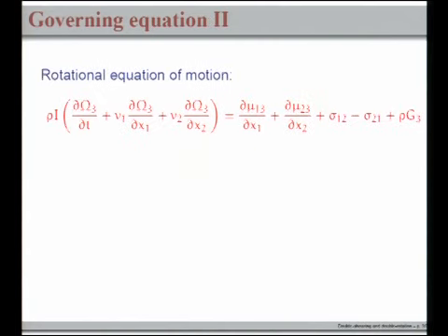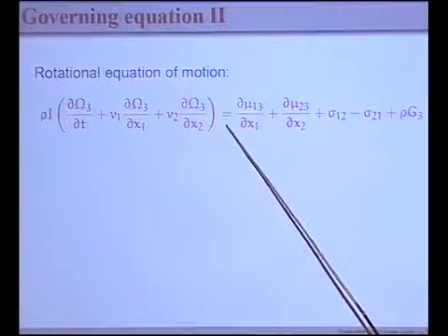Because granular materials change their density, the continuity equation will be important, of course, but not something that we need to talk too much about. The rotational motion, on the other hand, I guess I should say a few more words about that. For these planar systems, there is only one equation, so the three equations reduce to one. Can write it out in this way.